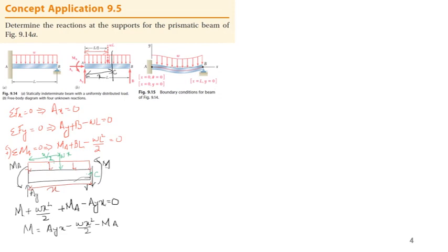Now let's find the equation of elastic curve. For the equation of elastic curve, I know that EI d²y by dx² will be equal to M(x).